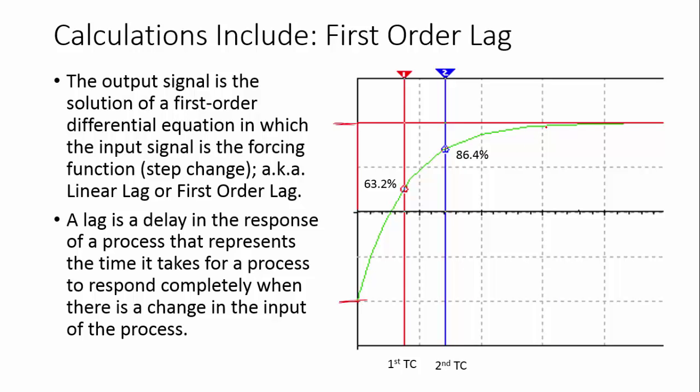And you read earlier in the text that this change, the response of your signal, should take around 5 time constants. What I did here was mark the first time constant, which occurs at 63.2%. The second time constant occurs at 63.2% of what's left over from the first time constant.